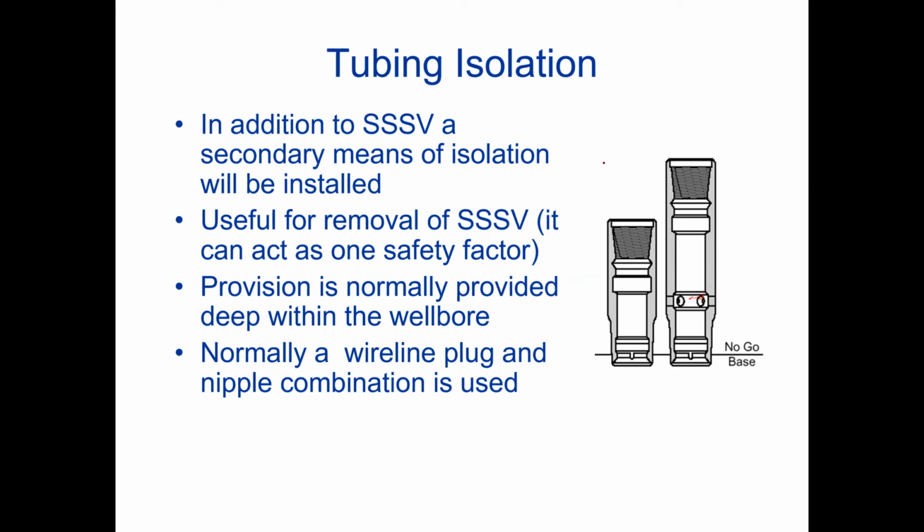The other facility that we put in the tubing is tubing isolation. This is in addition to the subsurface safety valve. The subsurface safety valve is a device that can close the well from inside, and became very popular after Iraq attacking Kuwait.